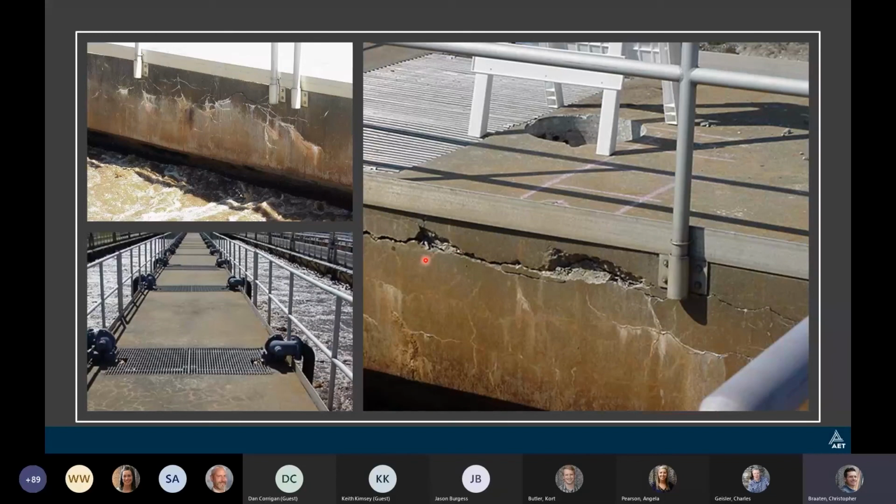But it's pretty interesting. And actually, I saw a presentation put on by the U.S. Army Corps of Engineers where they had a dam, I think it was in Tennessee, that had alkali carbonate reactivity, and they said their dam grew 14 inches. I don't remember how many years that took, but it's pretty crazy. They actually saw cut and relieved the pressure of expansion to increase the life for a little while. I'm sure it's going to be on their list of replacements shortly.